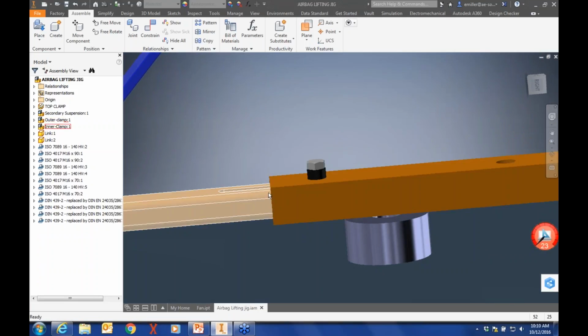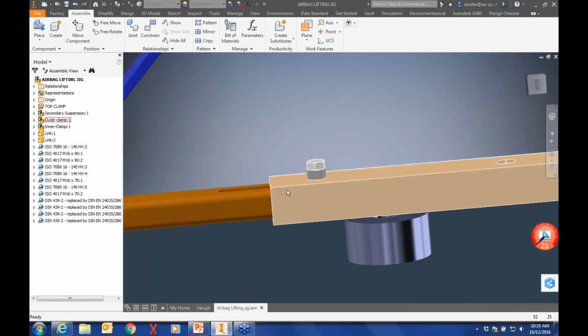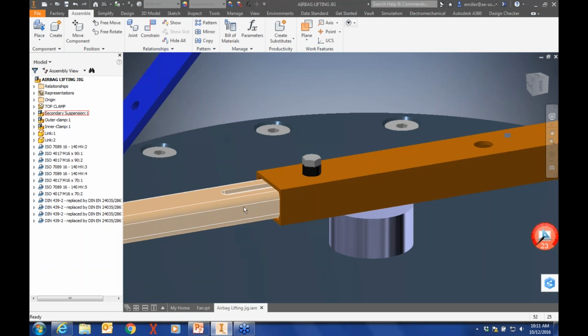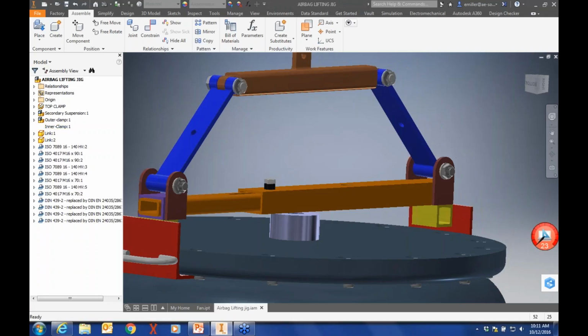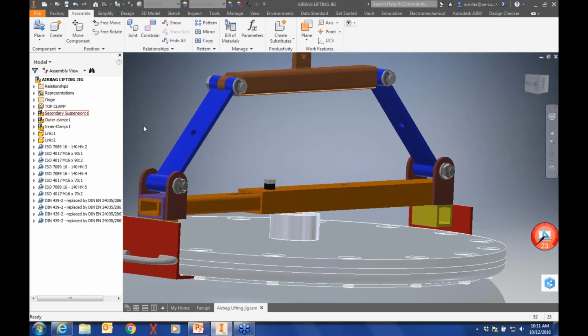And in this case, this is all going to be compressing into each other. So at least we can maybe assume that the rounds are probably not going to have a lot of effect because the force is going towards the center of the model. So let's go ahead and do that first before we even get into the analysis environment.